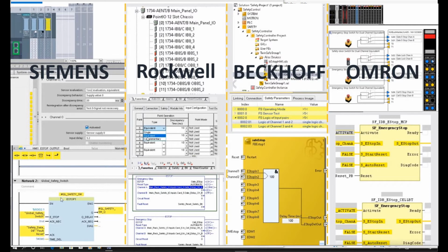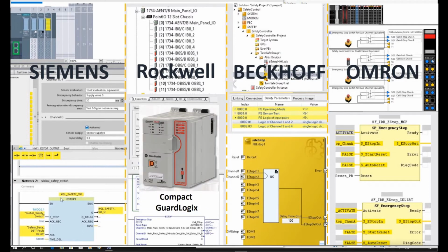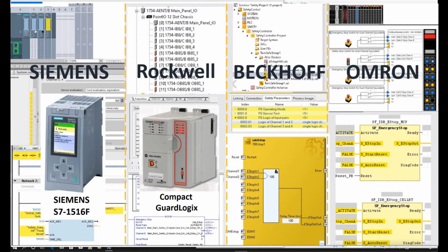That's because the standard controller and the safety controller for Allen-Bradley and Siemens are integrated together. For example, the Allen-Bradley safety CPU is labeled with ICE. The Siemens safety CPU is labeled with an F, for functional safety. So the standard PLC and the safety logic are all integrated together in this controller, so it's quite easy to exchange signals between the safety and the standard.